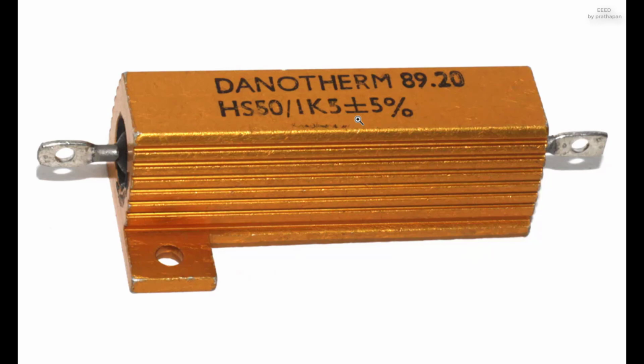If the average power dissipated by a resistor is more than its power rating, damage to the resistor may occur, permanently altering its resistance. This is distinct from the reversible change in resistance due to its temperature coefficient when it warms. Excessive power dissipation may raise the temperature of the resistor to a point where it can burn the circuit board or adjacent components, or even cause a fire. There are flame-proof resistors that fail, open circuit, before they overheat dangerously.